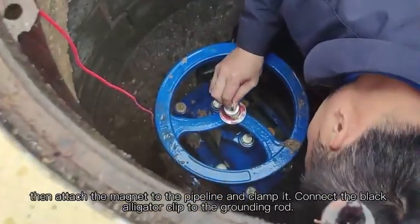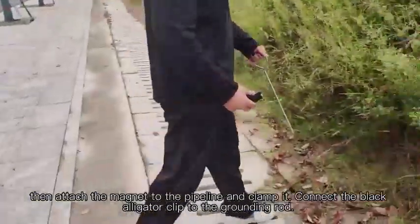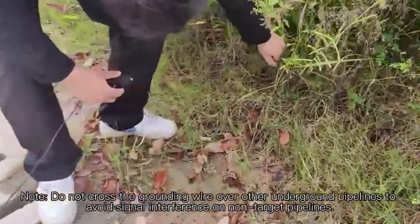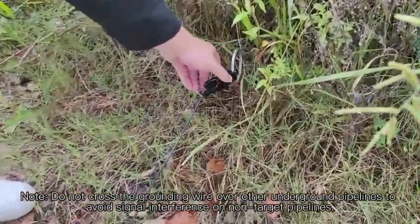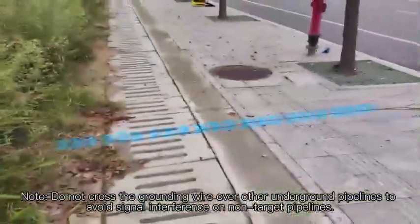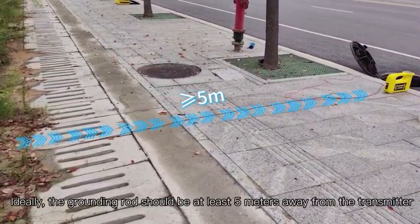Then attach the magnet to the pipeline and clamp it. Connect the black alligator clip to the grounding rod. Note: do not cross the grounding wire over other underground pipelines to avoid signal interference on non-target pipelines. Ideally, the grounding rod should be at least 5 meters away from the transmitter.